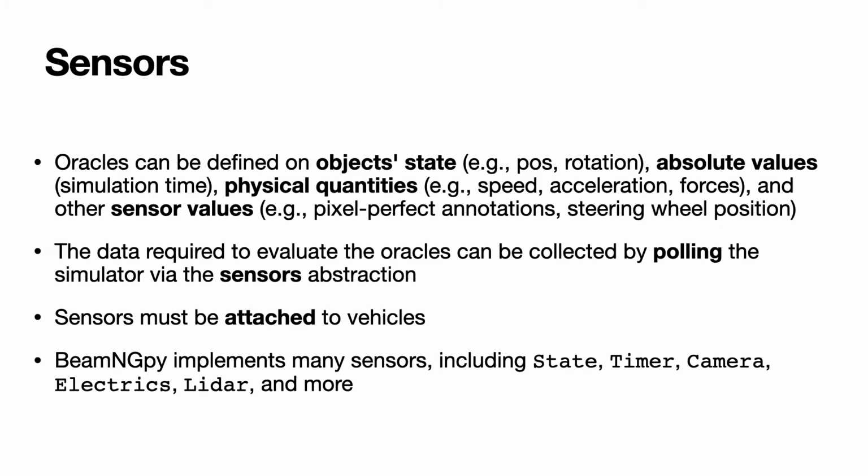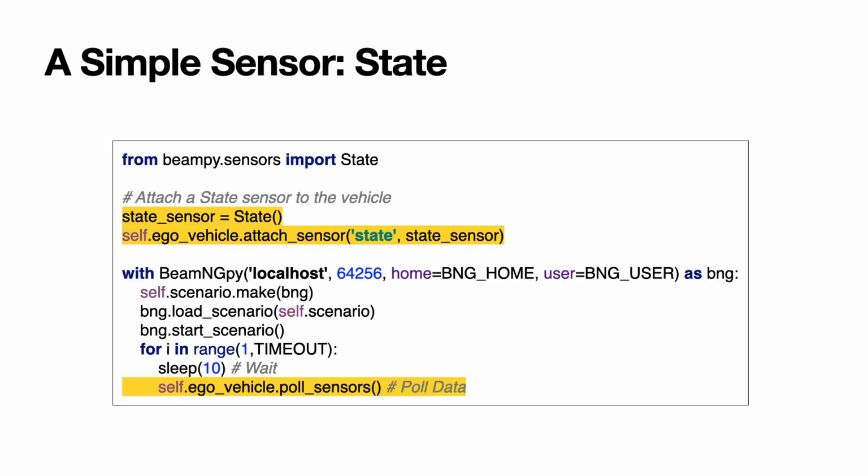These data that are required to evaluate oracles can be obtained by modeling the simulation using the sensor abstraction. So BeamNG.tech provides you this abstraction of sensors of different types: state, timer, cameras, electric sensor, LiDAR, sonar, ultrasonic, just name one, that you attach to the car. And when the sensor is attached to the car, then it can be read at runtime to collect data or to check properties. And this is what these runtime monitors indeed use.